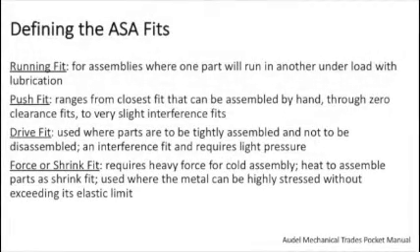So the first type of fit is called the running fit, which is for assemblies where one part will run in another under load with lubrication. The second type is called push fit, which ranges from closest fit that can be assembled by hand through zero clearance fit to very slight interference fits, assembly selective and not interchangeable.